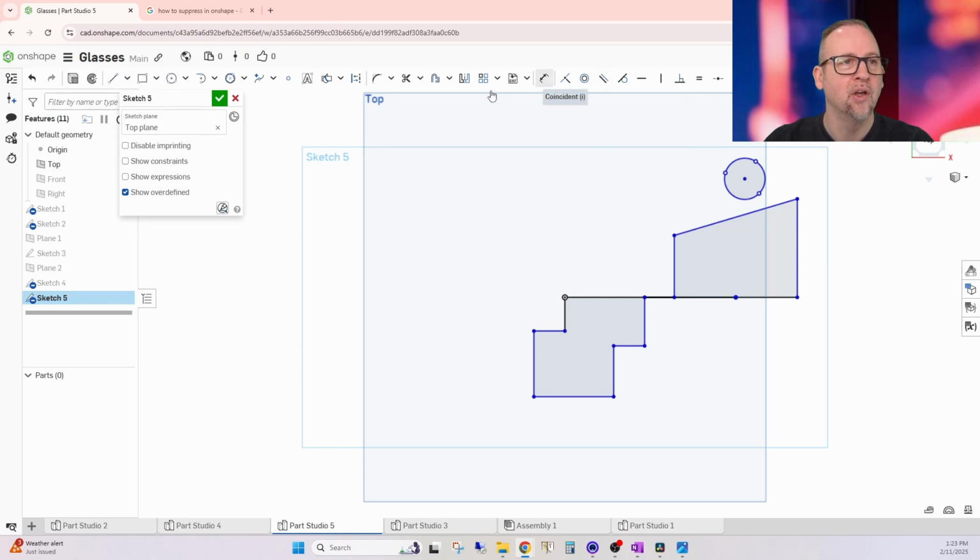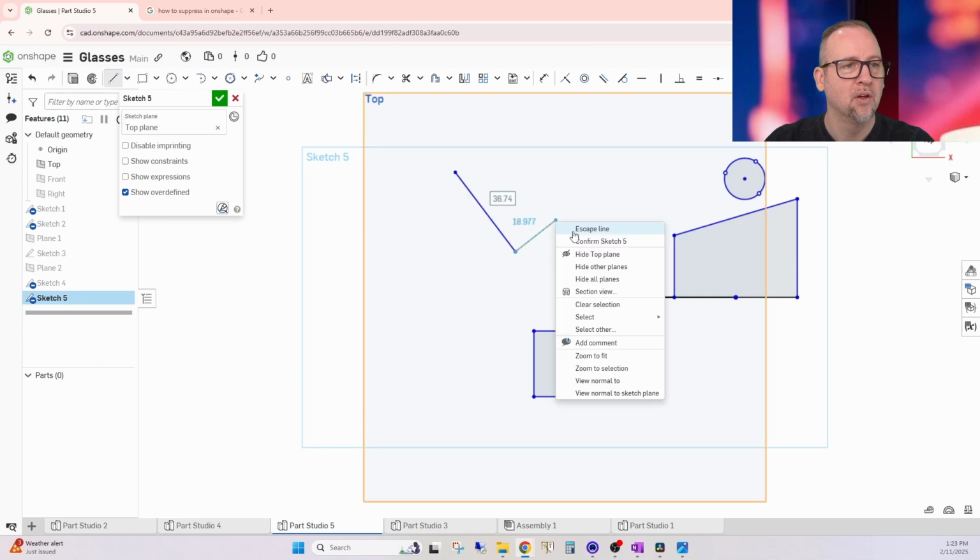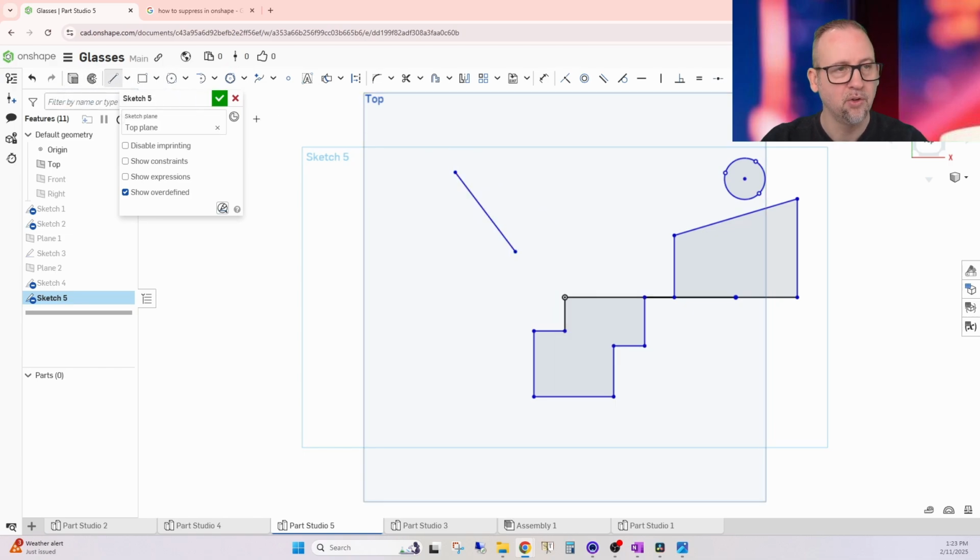And then we got parallel. So we have two lines just out in the middle of space. Okay, escape line, hit L. Let's go, we're not parallel now, and then I'll hit L to undo. So whichever one I want to be the first one, parallel, I would choose that one, and you see that one snapped to it, so now it's parallel. Okay, and now we could do coincident, so this one could be coincident to this one, so it's snapped right down to it, and these are still parallel.